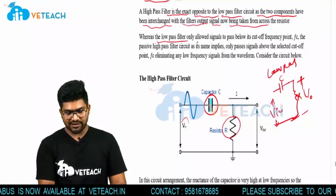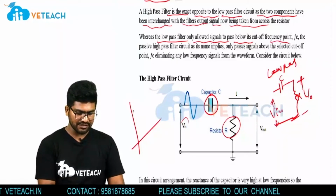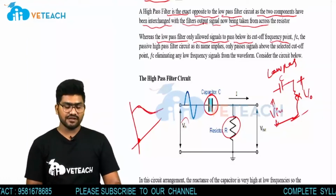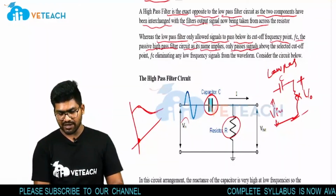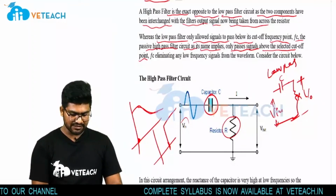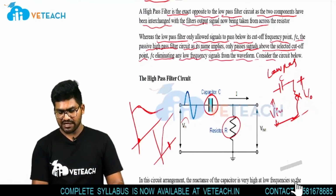Whereas the low pass filter only allowed signals to pass below its cutoff frequency point, if I see the low pass filter gain wave, it will allow signals at zero frequency, I mean at low frequencies. Its graph is like that, right? Whereas the passive high pass filter circuit, as its name implies, only passes signals above a selected cutoff point. So the signal can be passed above the cutoff frequency like this, or it can be drawn like this, by Fc eliminating any low frequency signals from the waveform.